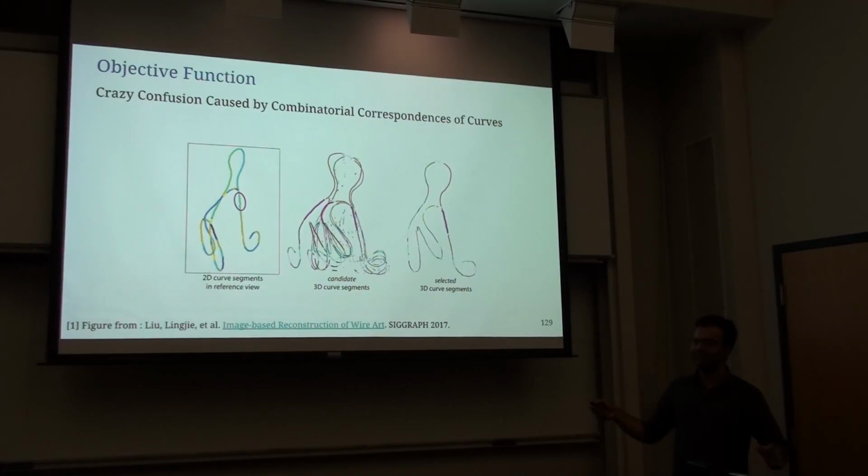This was an insanely involved traveling salesman's problem which they were solving, making sure things are continuous at each endpoint, so you can see. This thing takes like 10 minutes to solve, if we have to avoid things as well. So that's why the model-free method is so good for avoidance. But the model-based method is for someone who wants to chop trees off near wires, or wants to do parallel segmentation, or sag estimation, because they want to estimate if we need to reinforce the poles supporting the wire and whatnot. Okay, great.